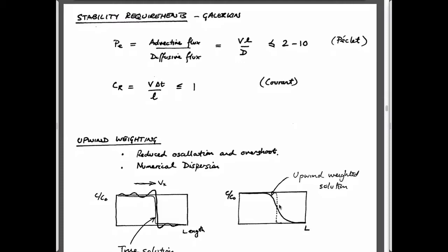So now we know how to get these elements generically. We can do it in one dimension, and in 2 dimensions. By extension of all we know about isoparametric elements, we could also do it in 2 dimensions for elements with 4 nodes, or 9 nodes for that matter, and also by extension to 3D as well. So we'll leave it there and not take that any further.